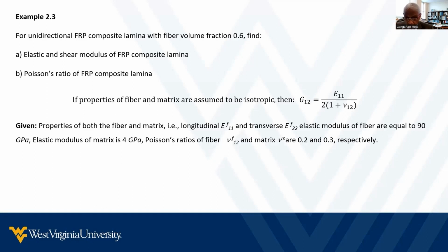In this example, we are using a fiber volume fraction of 60%, as we did in the previous example, to illustrate the point. This implies resin volume fraction is 40%. Repeat, weight fractions are higher than volume fractions due to higher fiber density than resin density, or higher specific gravity of fiber than the specific gravity of the resin.